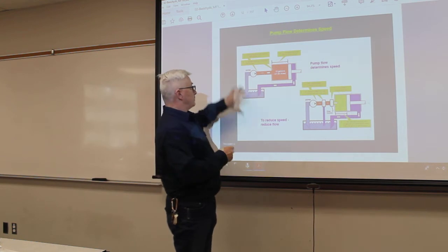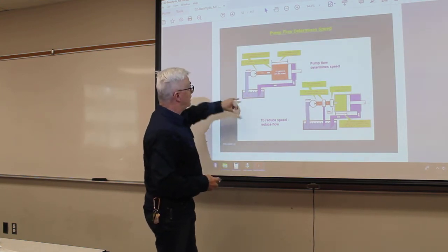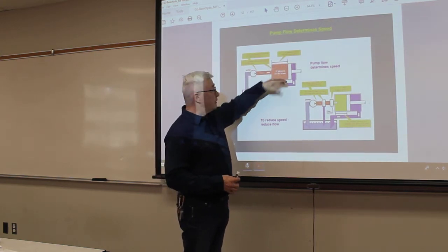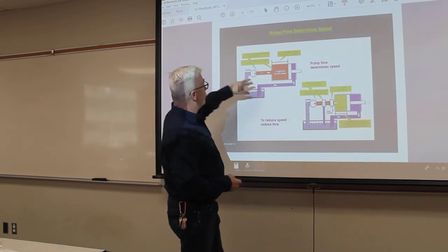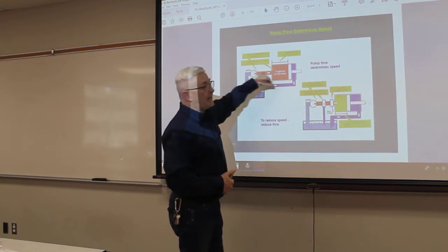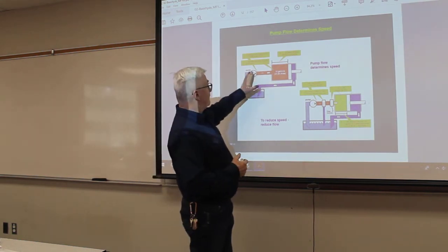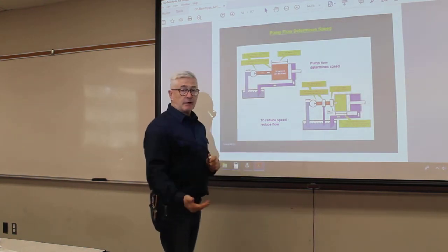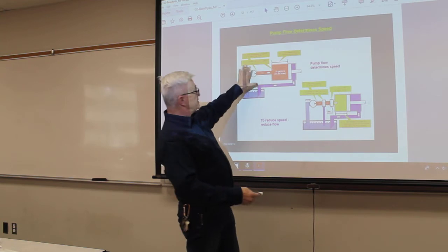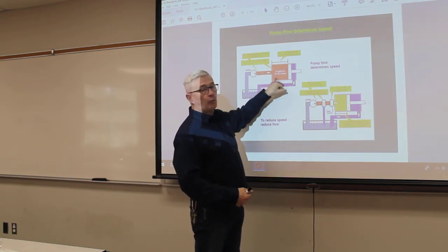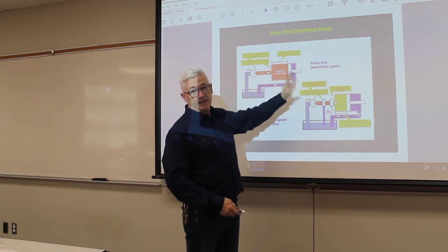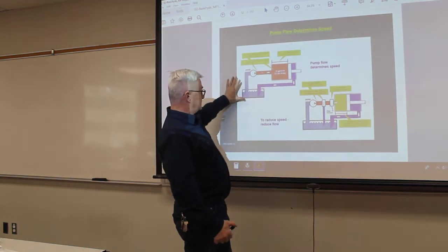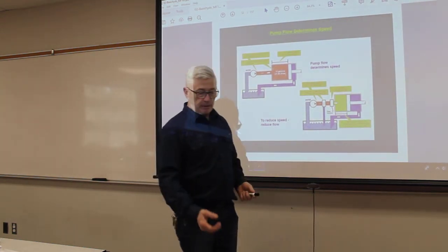All right, and again, it's in your handout, so you can look at it. We have our pump creating flow, and we're working against a piston or an actuator, and we're getting some work done. The pump is pushing out 10 gallons per minute, so we're going to move 10 gallons into the piston. It makes logical sense that, even though it's a huge piston, at 10 gallons per minute it's going to take 1 minute for that piston to fully extend. The fluid will just be returned back to the reservoir, and we have a very simple hydraulic circuit.